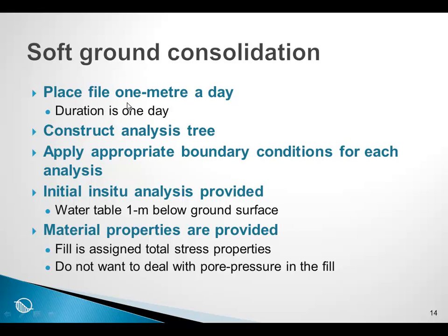So here's a summary of the exercise. Place the fill 1 meter a day. In other words, in our time stepping, the duration is 1 day. We need to construct an analysis tree, and we need to apply the appropriate boundary conditions for each of the analyses in the tree.